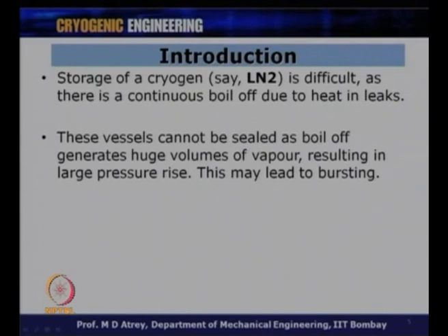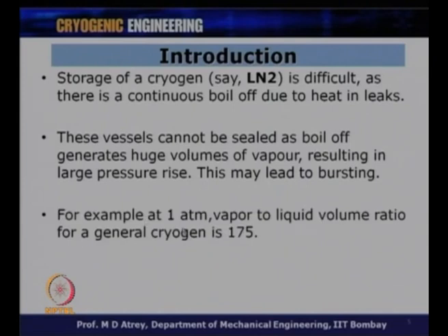So, we want to reduce this boil off. We can't of course keep these cryostats or cryo containers completely closed. You can't have sealed lids over there. The boil off will always occur because the heat inleak will always occur, although we can minimize these heat inleaks. For example, at 1 atmosphere, the vapor to liquid volume ratio is of the order of 175. Can you imagine this?